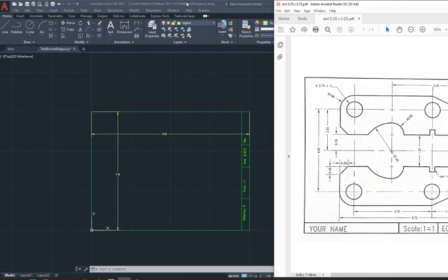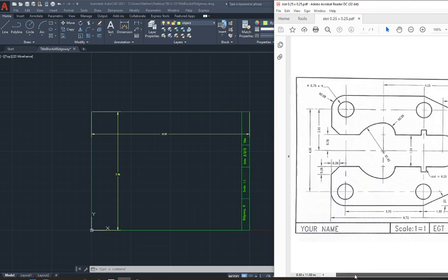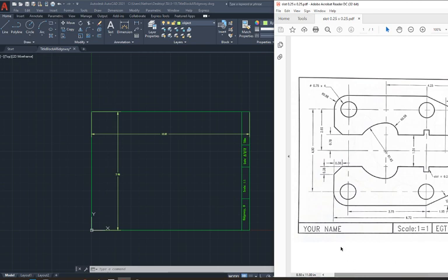But on your paper that you're holding in your hands, it'd be 4.25 inches. So you're basically saying the scale factor would be the fraction that you would say the scale of this to this. If every 1 inch is 2 inches for the object, it'd be 1 to 2, for instance.